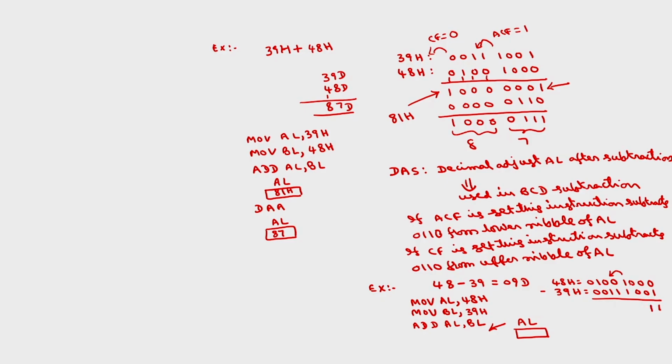And this also is the same thing. 0 minus 0, no borrow is required, but it has given 1 to the previous stage, so to pay that it has to take a borrow so that it becomes 2. Out of this 2, 1 is given here, and 1 minus 0 is 1. This 1 has already been given, so this becomes 0 minus 1. To perform 0 minus 1, it has to take a borrow from the upper nibble. A borrow is required from the upper nibble to the lower nibble, which implies the auxiliary carry flag is set. So after taking the borrow, what will be the result? This becomes 2, 2 minus 1 is 1.